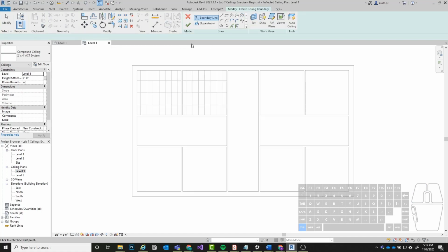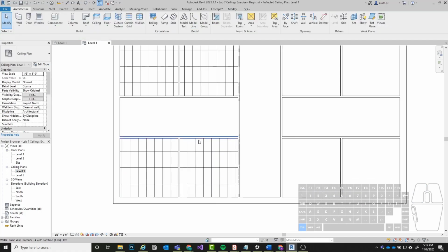sketch ceiling mode. All right, so if I were to go here to the sketch ceiling mode, and I would choose my rectangle tool and then click here, what you would want to do is now click the green check mark to finish this ceiling here so that you just get this room by itself. If you were to go ahead and draw in this ceiling over here at the same time, so I have two rooms now drawn, and then click OK, you can see that they're linked together. So whenever I toggle to them, it highlights both.